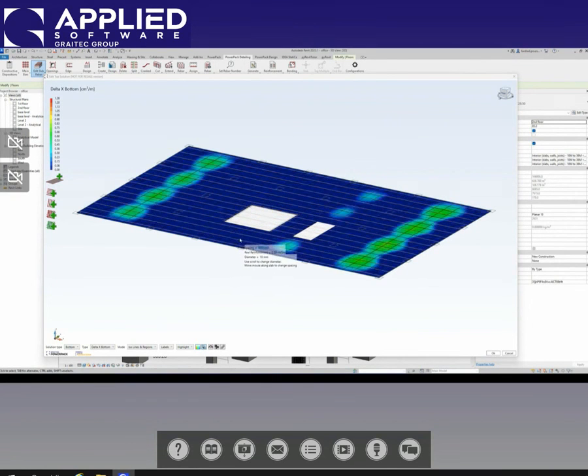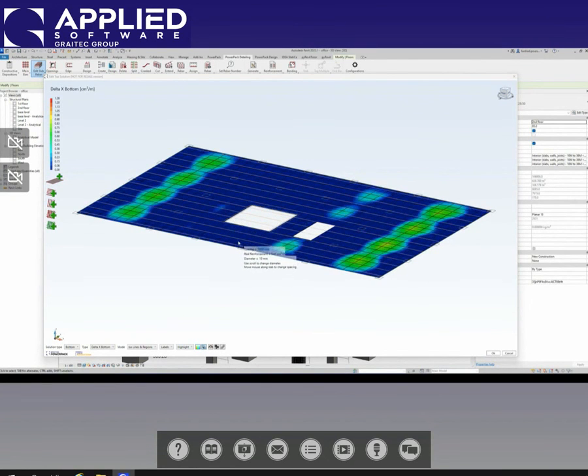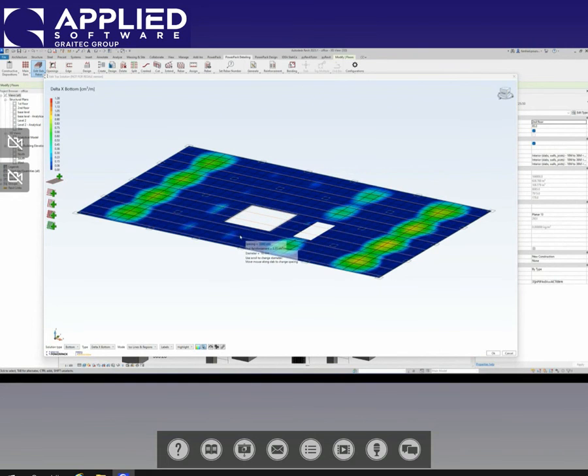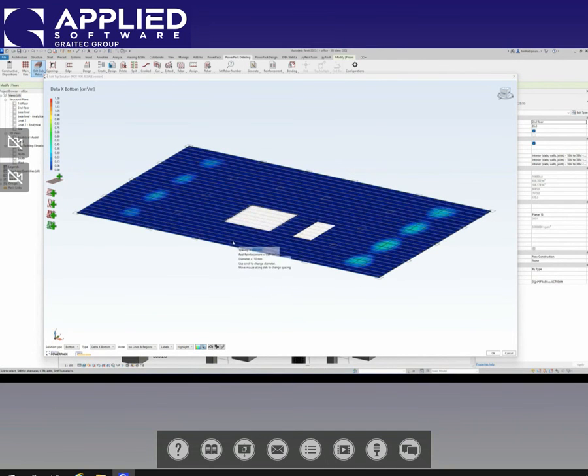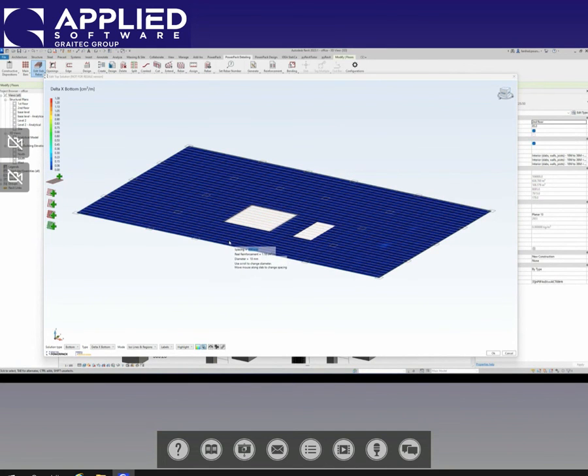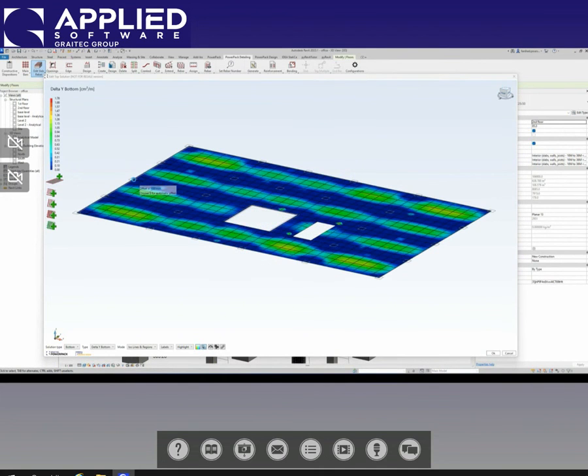So when I'm putting my rebars farther away, because I have less rebars, less area of steel, as you see, I'm not covering my theoretical rebars. But when I'm putting them closer, you see, at some point, I'm covering it fully. So here, I'm going to decide that my spacing is 600 millimeters, and I will click. And now I've added that direction of rebars, and now we're going to be working in this direction, okay?